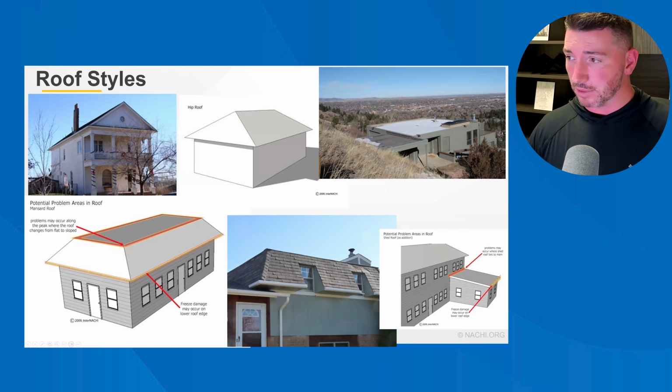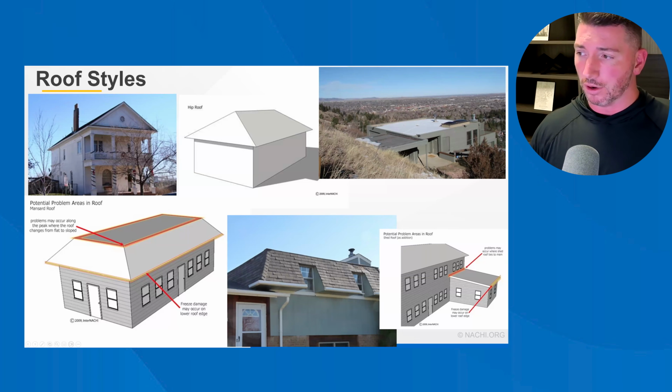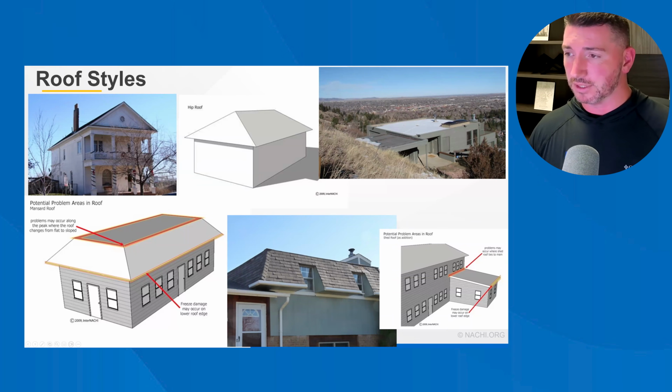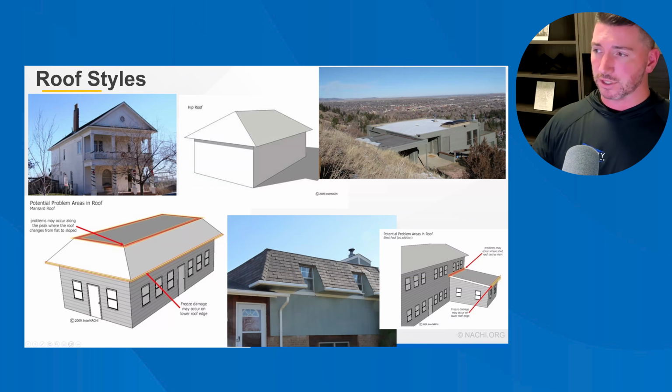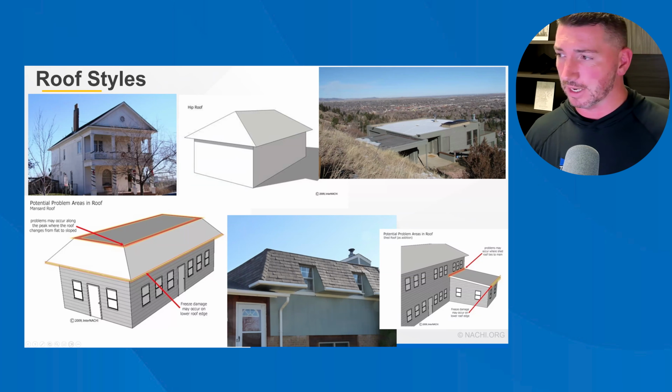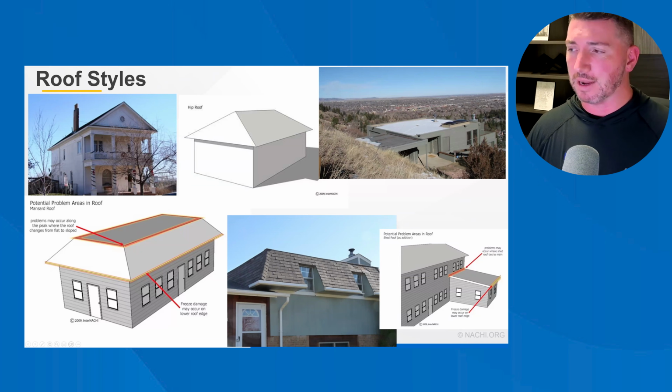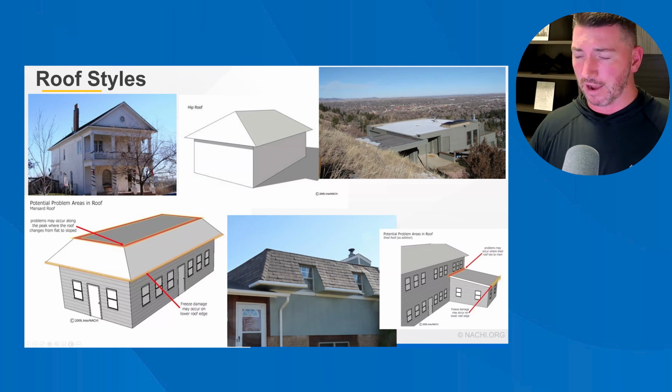And you can see that in the middle one, there's a hip roof. Again, now you see that the walls are all rectangles and none of them follow the ridge all the way up to the top of the roof. There's a roof slope covering that area instead, and the structure of the framing is a bit different because your normal gable roof traditionally has a ridge beam, rafters that run from the ridge beam down to the double top plate. On a hip roof, you've got hip rafters that run diagonally out to that corner, and then you have these other rafters.